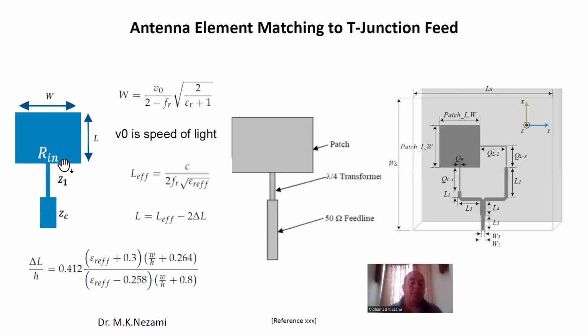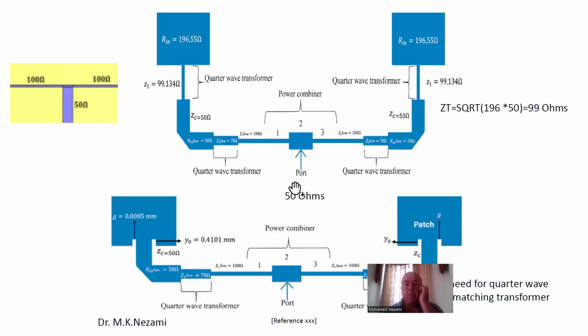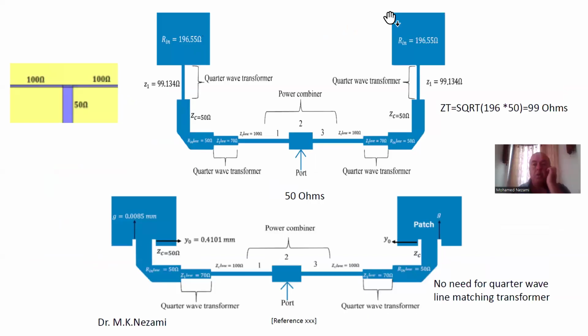Okay, like for instance, in this case, watch this. So we can have antennas like this type here. We can have antennas where the impedance can come in and you're forced to use something to transform the input impedance of the antenna, which is in this case about 200 ohms, back to 50 ohm.